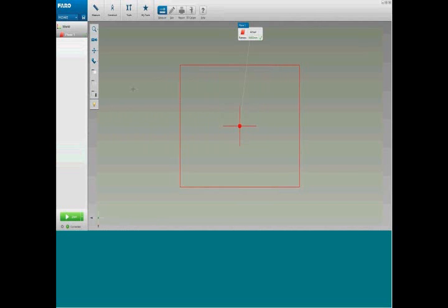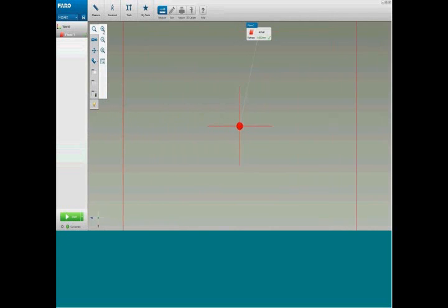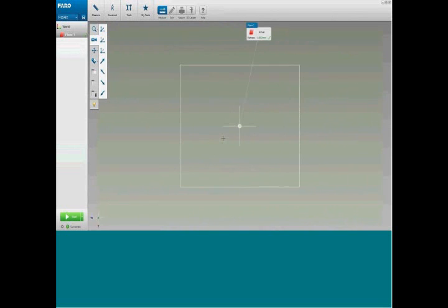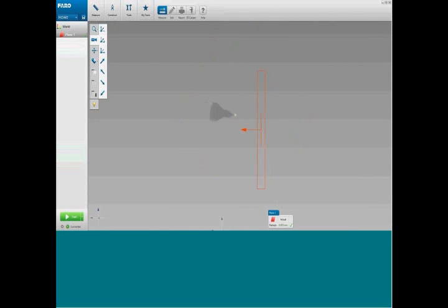Okay, I can now show you some of the functions of the sidebar menu. In here we have the zoom menu, so we can zoom in, zoom out. We can reset the view, which will reset to 3D. Clicking on a plane will align the view to that plane, like so. We then have the camera menu, which has some preset views. So from the X direction, the Y direction, and the Z direction. We also have the 4 basic isometric views.